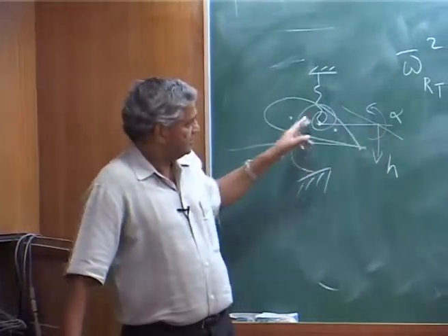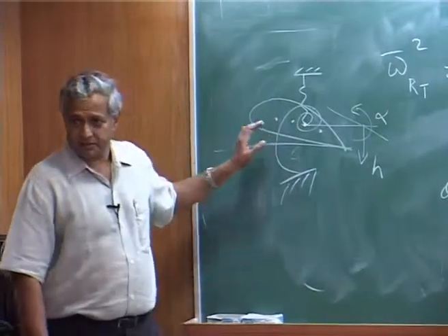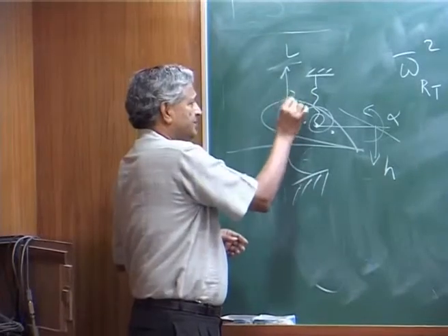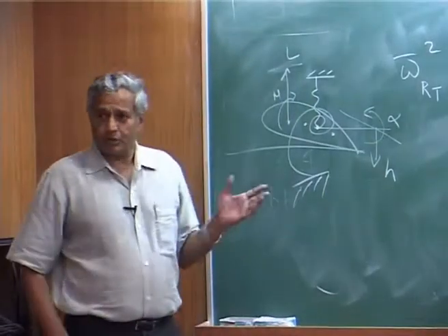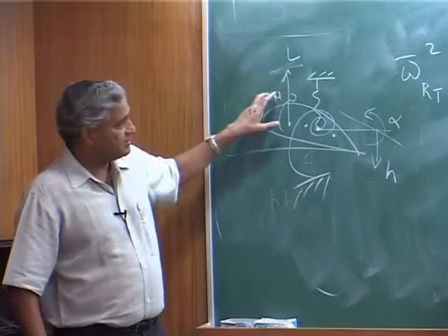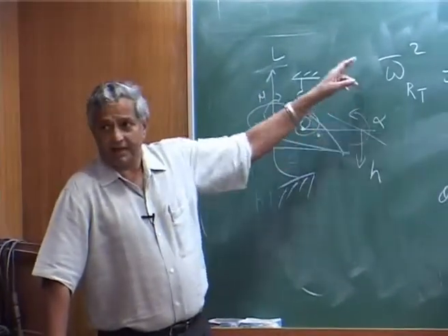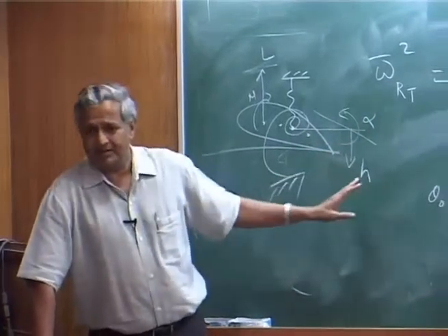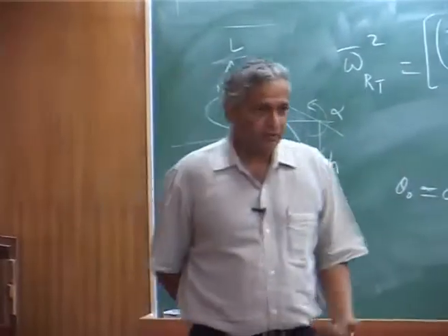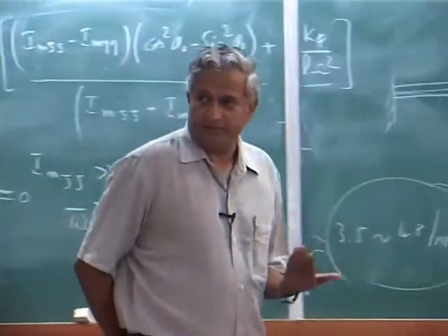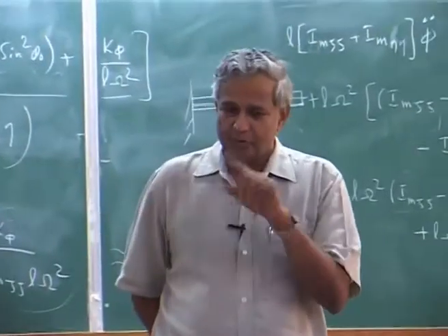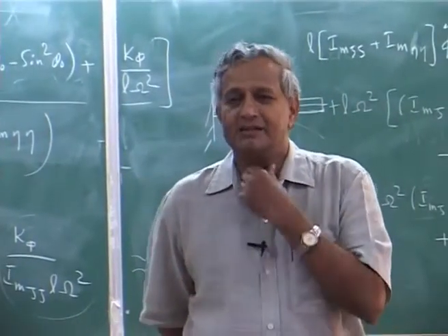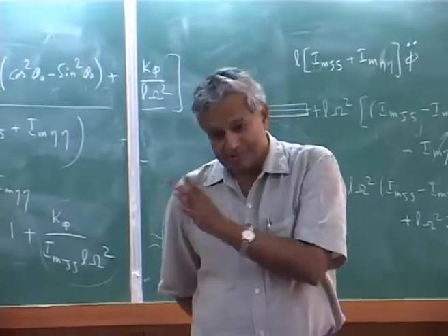So you will get the lift and moment expressions about the quarter chord, and these expressions will be a function of alpha, alpha dot, alpha double dot, h, h dot, h double dot, h triple dot. So you will find everything, and this theory is by the vortex model. This is unsteady aerodynamic theory. This is not taught, suppose this is what I am telling you.